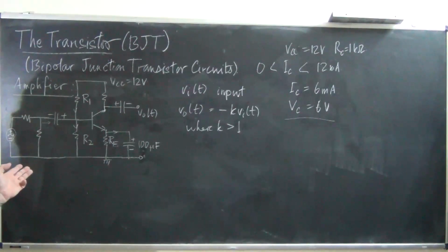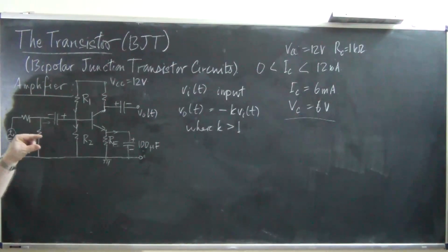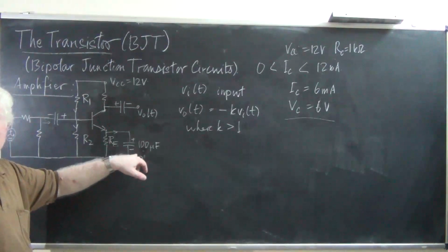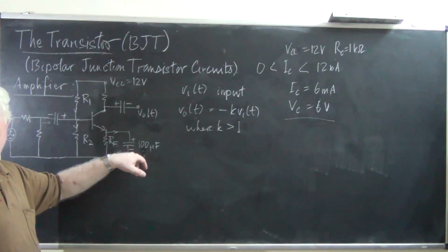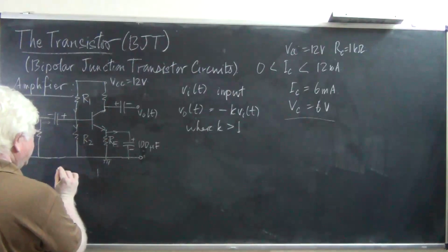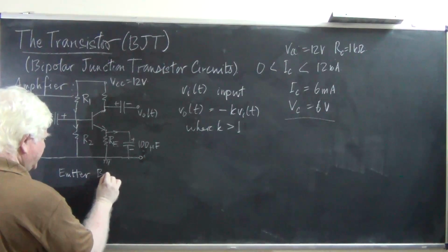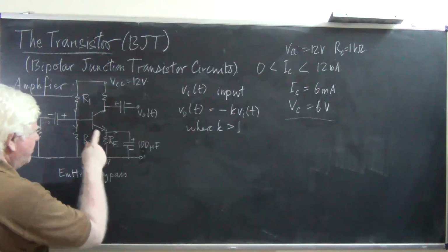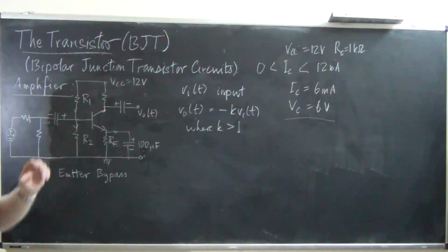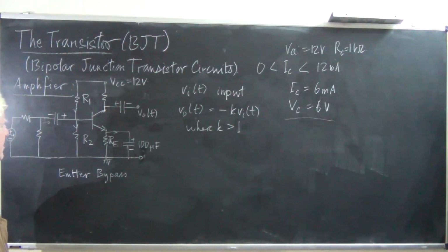Really, what we want is a sufficiently weak signal of only a few millivolts peak to peak to enter the circuit. And all this is required only when the amplification really goes up on account of placing an emitter capacitor over here, what is called a bypass capacitor. Emitter bypass, to bypass the AC signal while not affecting the pathways of the DC signal. So more details, tabulation, calculations, etc. are given in the handout, and this is all we need to cover in this presentation.